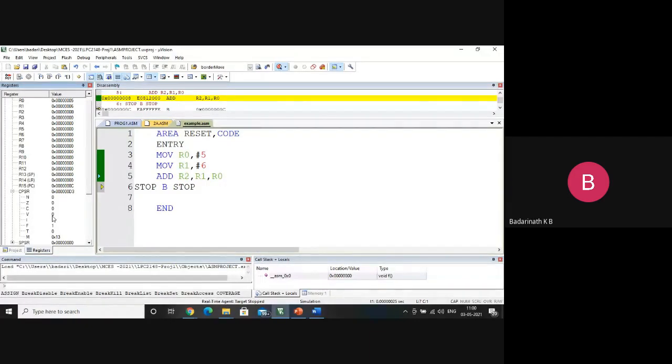There is one more flag called the overflow flag, which says that you produced an answer which cannot be held by the resultant register and you lost the meaning of the answer. We will go into detail about these flags because they are crucial for an assembly programmer to implement their logic. If you want to use if and else, for loops, or a while condition, everything in a lower level language is based on these 4 flags only.